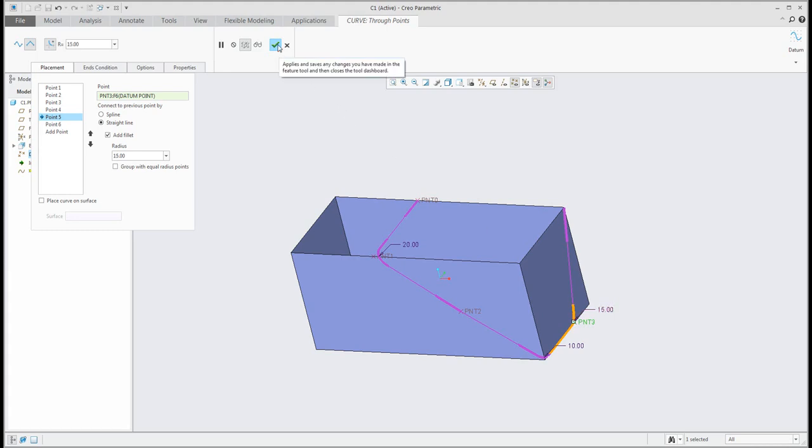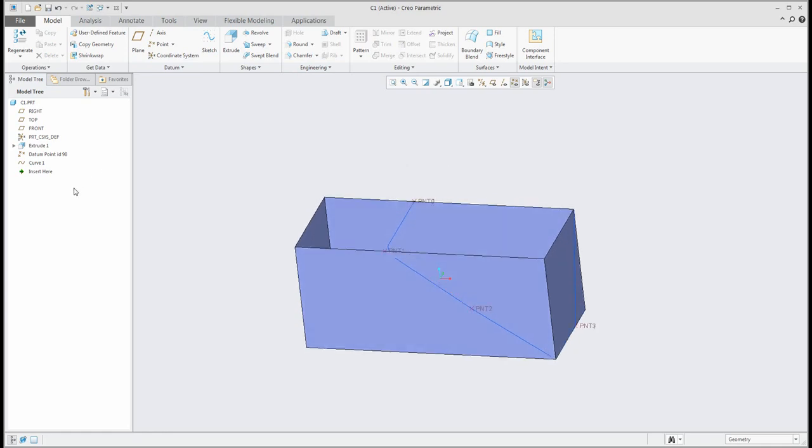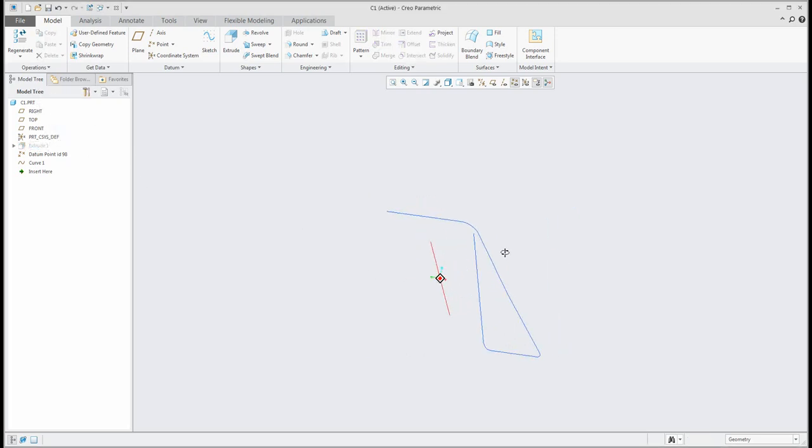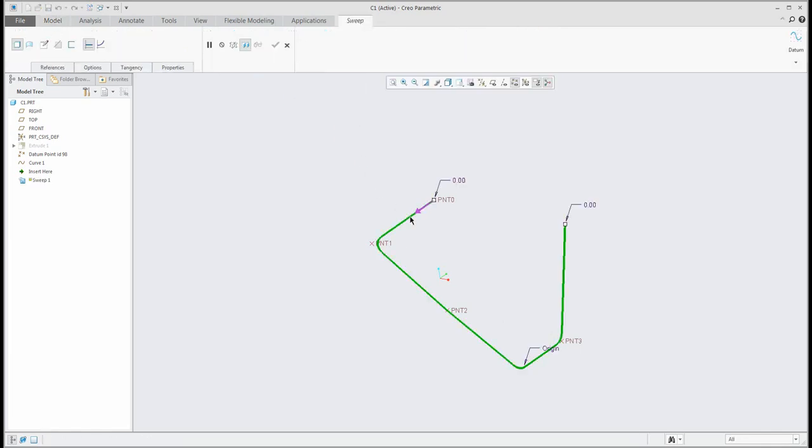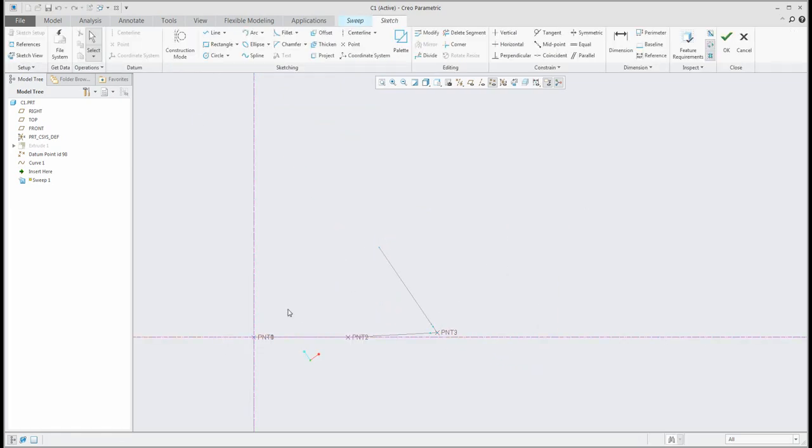What is it good for, again? I have specified my boundaries or base shape. This base shape I can hide, and the system will create for me a 3D curve based on the first extrude feature and datum points. And over here you know that it is possible to use the sweep feature, for example, and specify the custom shape, open shape or closed. You can use the palette.